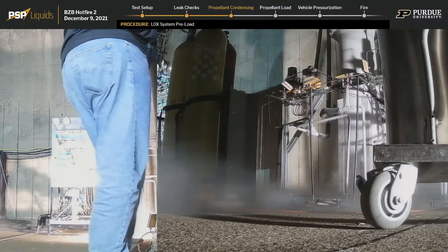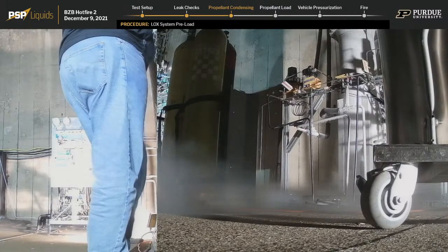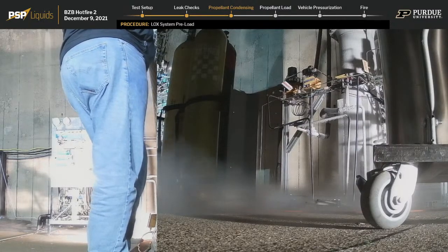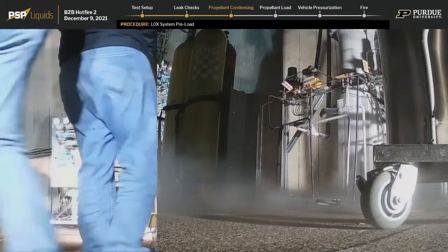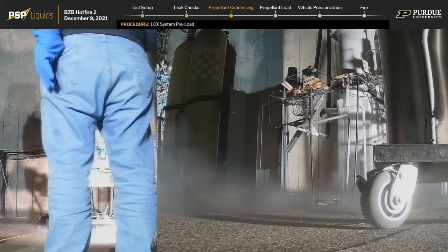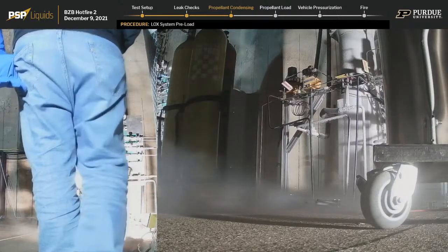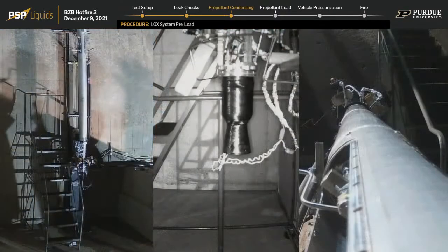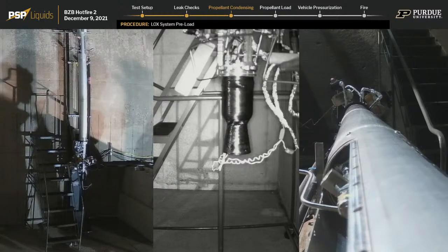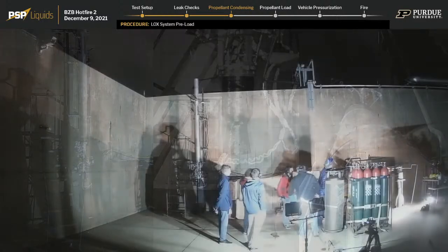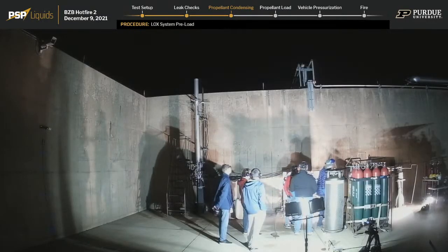Yes. The dewar pressure is at 70 right now. Over. The ablative is not providing any meaningful structural component. Copy. That is all provided to us by the overwrap that you saw with the carbon fiber. So yes, we would just lose thrust because the throat area gets larger, and our engine performance would degrade. And that's, of course, one of the things we're trying to test with this.